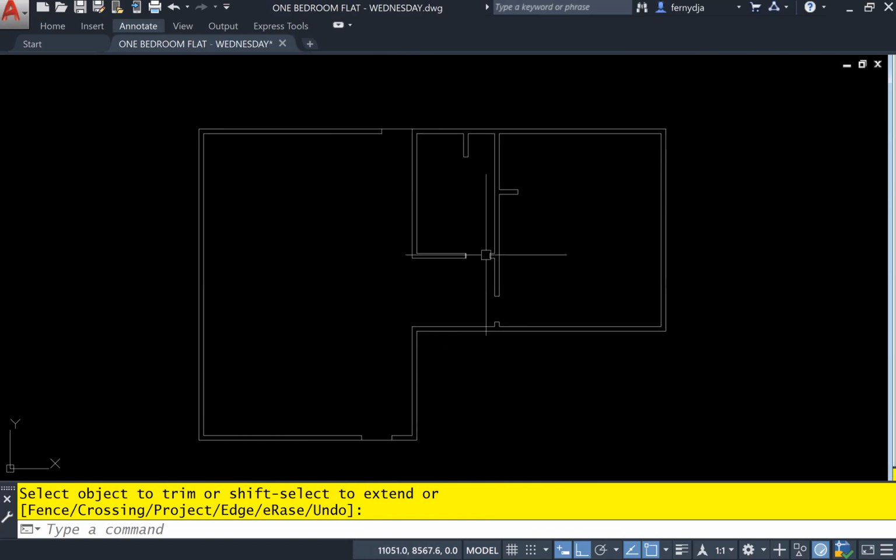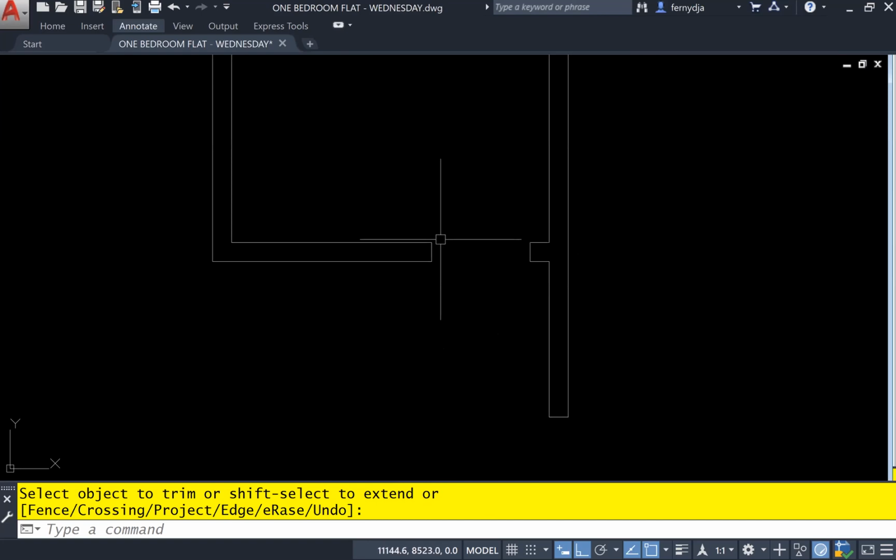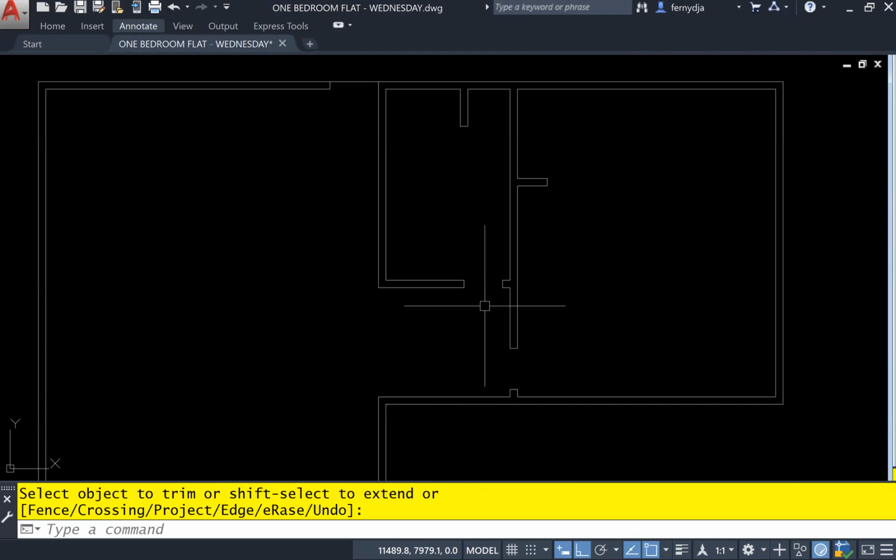Yes, we could have a step down inside the house. And if that was the case, we would leave the line there. So for example, if you had to step down to go into the bathroom, then we would do that. Sometimes people have a step down kitchen. They would leave the line level to show that you actually step down from one level. But in this case, across the building is the same floor level. So we don't need to leave any line in there except for the front door and the back door.